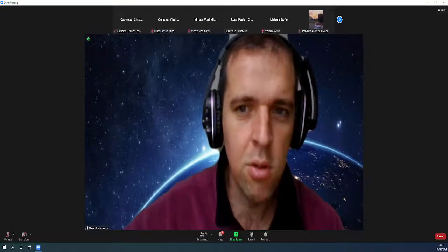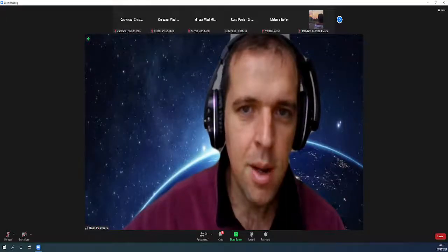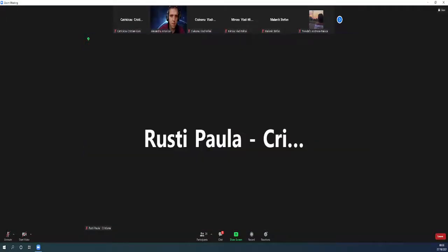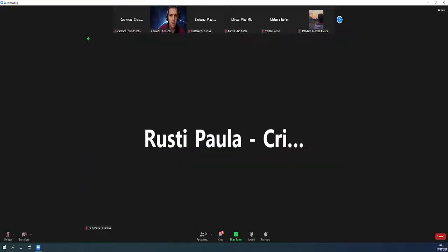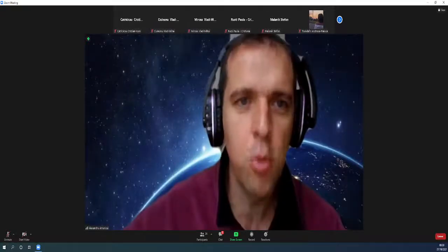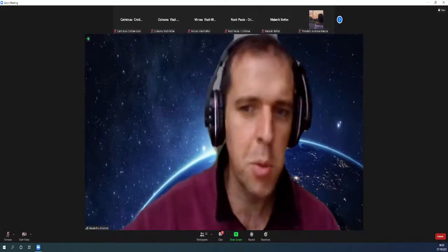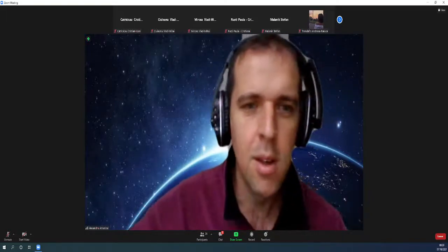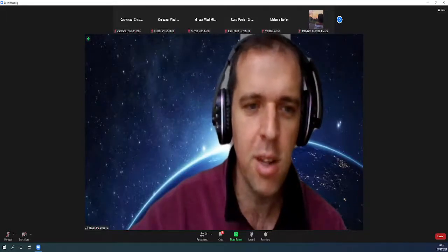So try to go the simple way. I mean, I could write an if instead of that. Yes, you can write an if. And you don't have to put the ORs in the sensitivity list. You can go with commas. And it's a signal actually on 2 bits, so you don't have to write the 0 and the 1.